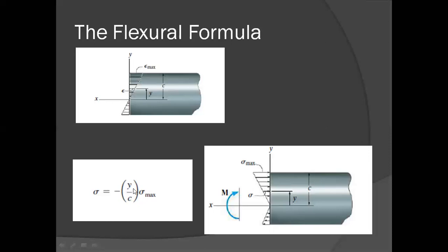Again, we are measuring every distance from the neutral axis. We already know from the earlier courses on mechanics of materials that all the distances are to be measured from the neutral axis. Say, for example, an axis which is perpendicular to the neutral axis, let's suppose that's the y-axis. At the neutral axis, the stress is zero. As we go above the neutral axis, the value of y is positive because we are treating y to be an axis perpendicular to our neutral axis.